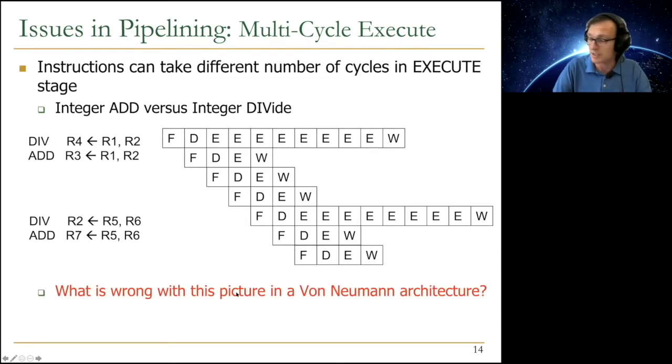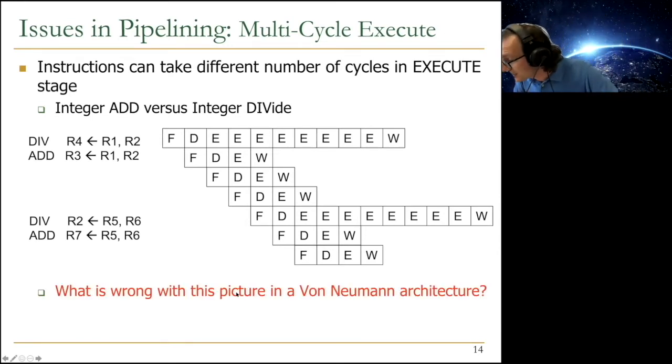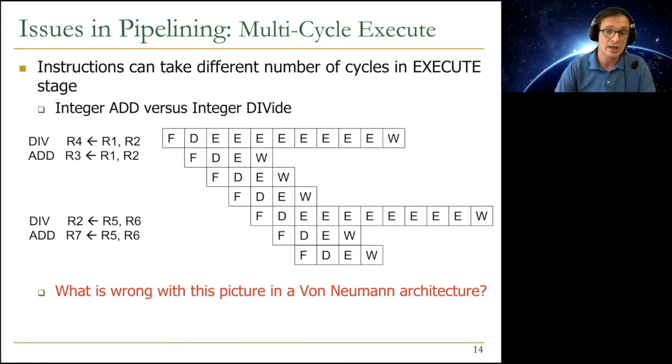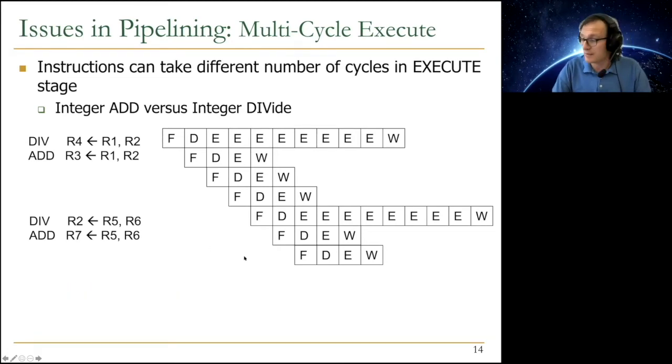So before that, I think there's one question over here. I need to handle the questions over here so that they don't get in the way. Basically, how can an instruction stay in the same part of the process if it takes multiple cycles for execution? Well, it can stay because you may actually latch intermediate results, right? It could be a pipelined execution unit. So if you have an eight cycle pipelined divide unit, for example, then it's just like another pipeline stage. You have 8 stages over here. If it's not pipelined, you need to make sure that you have a signal that says execution unit is done, basically. So there are multiple ways of handling it, just like we discussed with memory or any other pipelined execution unit.